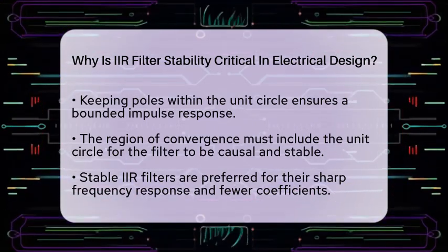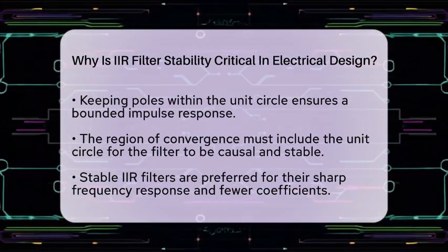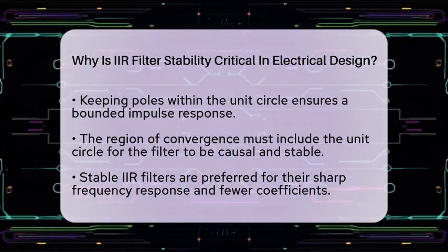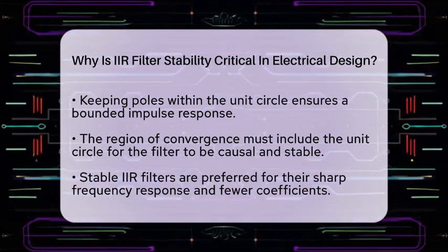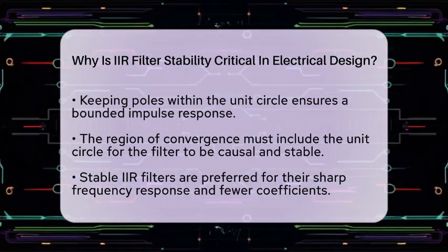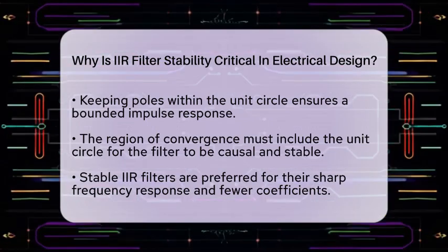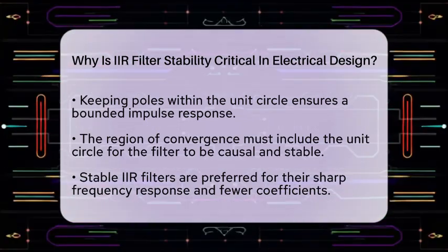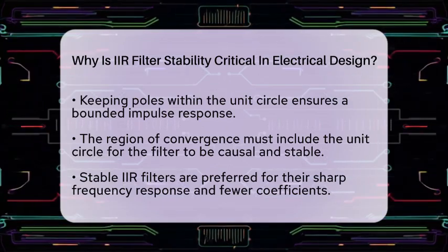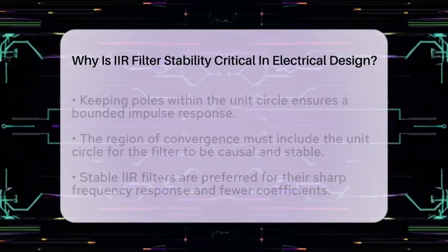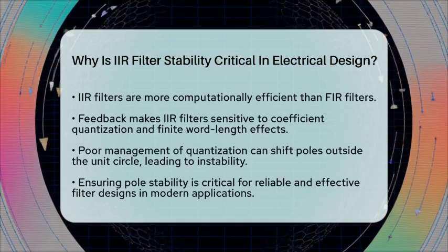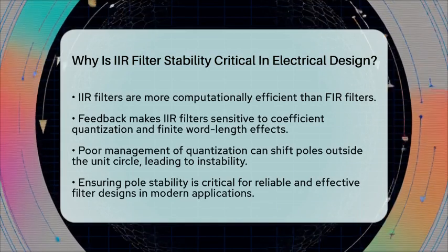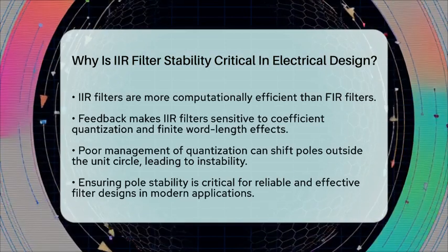In practical terms, stable IIR filters are often preferred in many signal processing applications. They can achieve sharp frequency response characteristics while using fewer coefficients, making them less computationally intensive than their finite impulse response counterparts. However, the feedback nature of IIR filters makes them sensitive to coefficient quantization and finite word length effects in digital implementations.